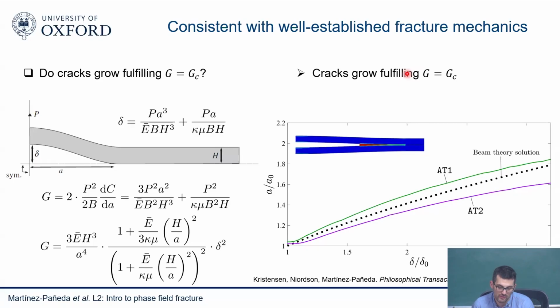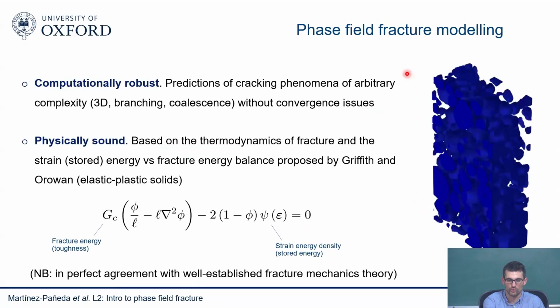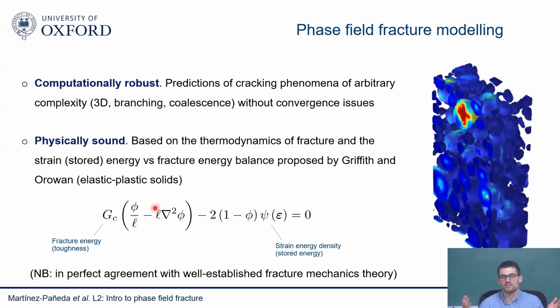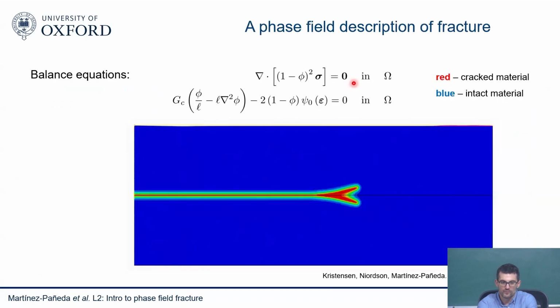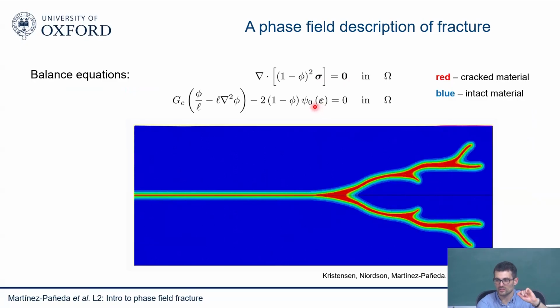So I think the main difference that I find with phase field and other non-local continuum damage type of models is that everything relies on a length scale, which you'll see the value of later. Other approaches are also non-local, but phase field is also based on fracture mechanics theory. So everything doesn't relate to some critical damage parameters that we don't know. Everything is based on the length scale and the toughness. And we have extensive databases of material toughness. That's on the physics side of things. On the computational mechanics side of things, there are some benefits related to the fact that we are solving the damage as an independent variable with a different PDE, because you add some flexibility on the computational side. I will discuss that later on.